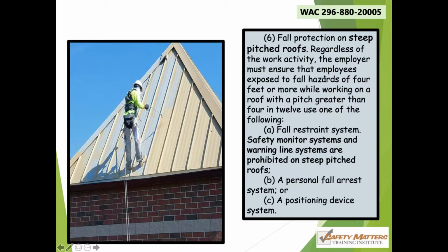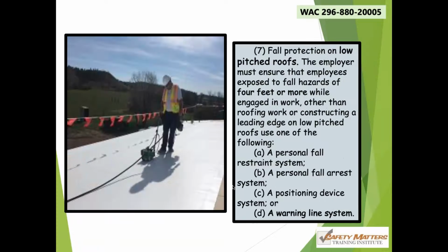Above 4 feet, if any worker is exposed to hazards at 4 feet on a steep pitched roof, what do we have to do? Safety monitor cannot be used. Warning line system cannot be used. They need to be in a restraint system or an arrest system or using a positioning device that will stop their fall in just 2 feet. Positioning devices need to be situated so they stop your fall within 2 feet.